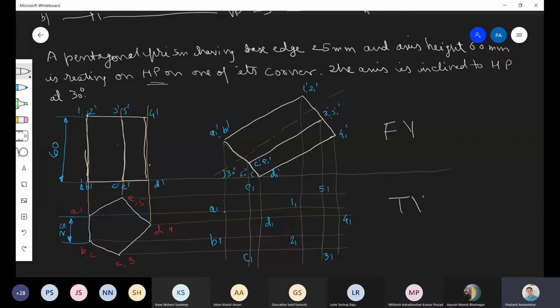This is which view? This is top view. Now in order to draw this top view, we will look at this object from the top. From here we will look, and we will write here T. So looking at this view from the top will enable us to draw this view. How will this look? Who will tell? When we look at it from above, we will understand what needs to be joined to what. Okay.